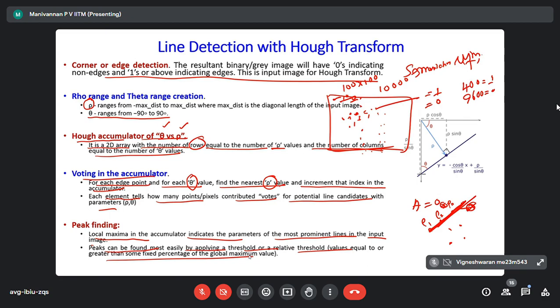With this, because of the image, light-based sensors are the most important sensors in an autonomous vehicle. First one is the camera, next one is lidar. The camera gives a more detailed image, but it is computationally intensive. It can detect color and also grayscale level, with the highest spatial resolution. Spatial means the smallest distance it can find. That depends upon the number of pixels. The higher the camera pixel count, the finer detail of the object in the scene it can see.